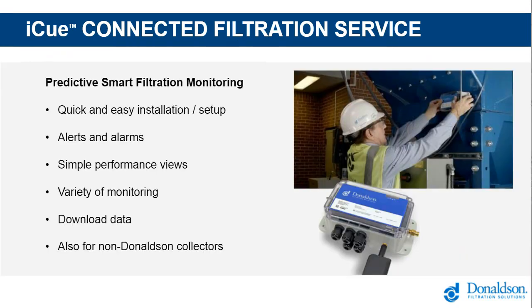So here you can see how simple it is to install the Donaldson IQ and get connected. Really quick and easy. And you can see from the photograph here, a person actually at site fitting the IQ gateway to the collector. It is magnetically attached to the collector. There's no drilling, so it's simply magnetically attached, linking up then the compressed air as a minimum and the delta P connections, and your smart monitoring is then underway, allowing you as the customer to focus on your core business, and then Donaldson would show up as and when required and as agreed.